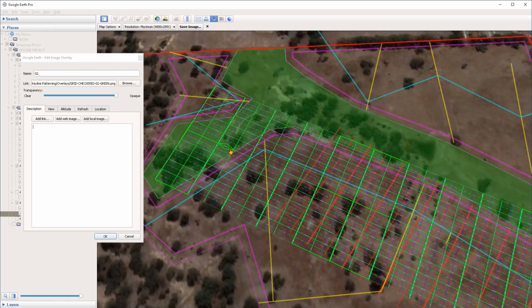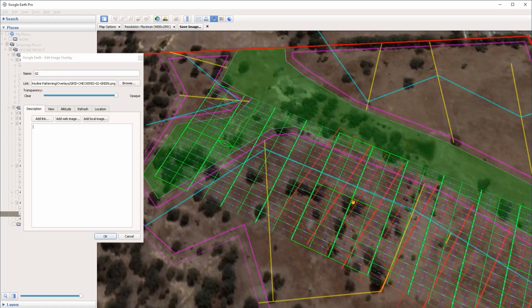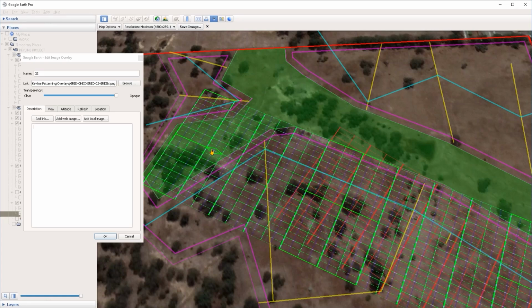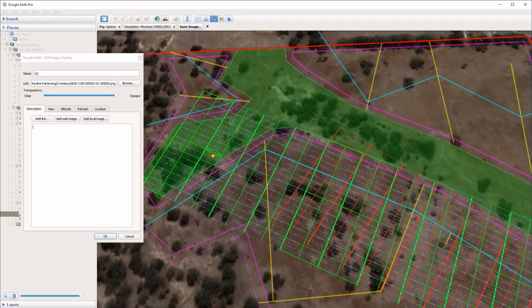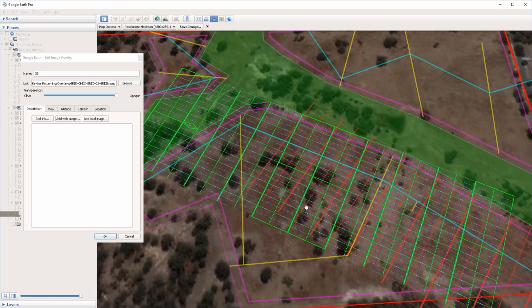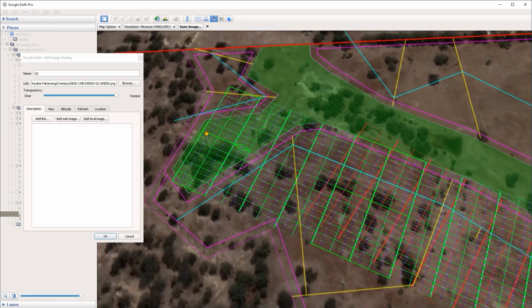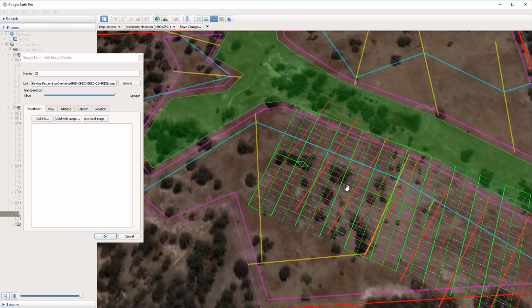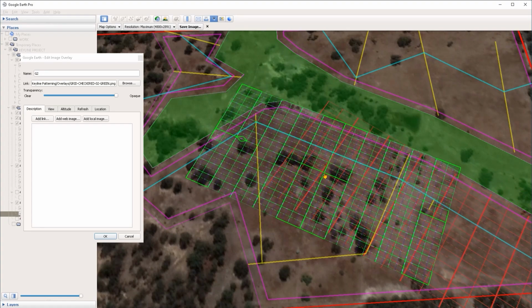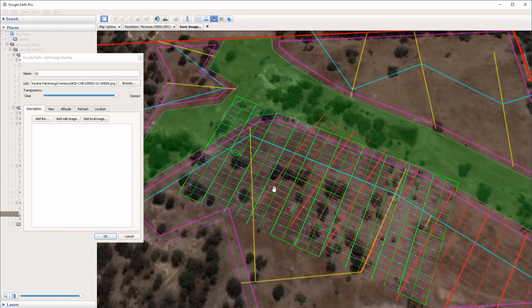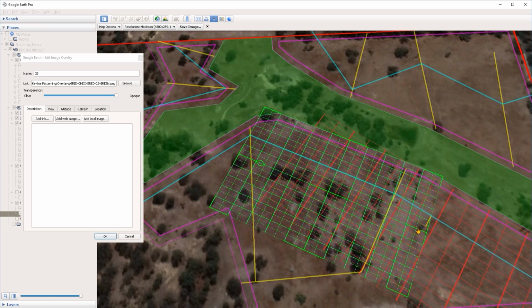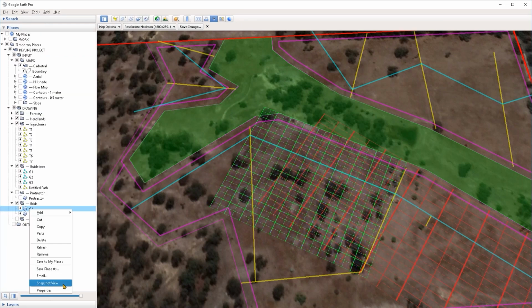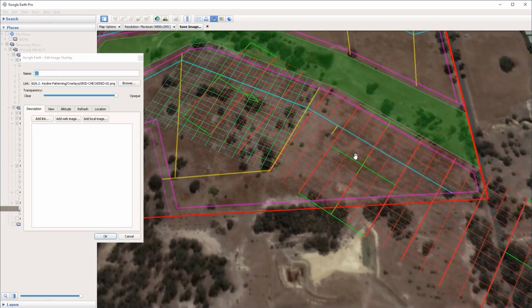Make sure not to scale the grid because at the moment it's scaled accurately to give us 15-meter intervals. So make sure not to scale it. You can rotate it and move it around, but don't scale it. So I'm going to position the grid here. You can scale it in the other direction if you want. Just don't scale it on this axis or on whichever axis you use to determine the offset spacing. So I'm going to scale it down a little bit so it doesn't intersect so much with our other grid. And I'm going to do the same for the red one.